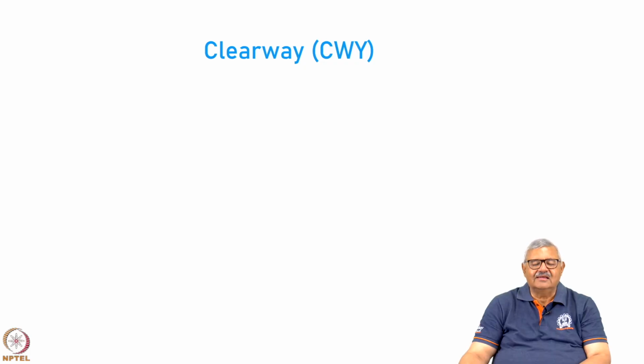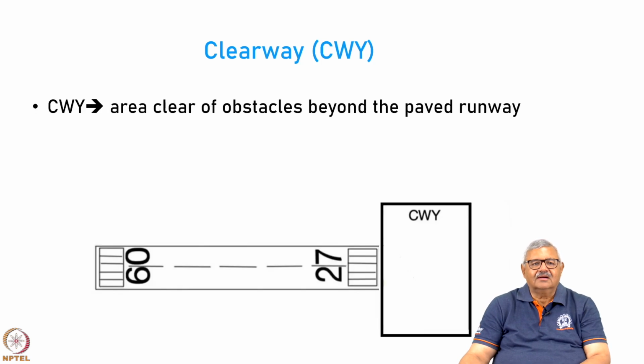Now, there are some concepts which we need to understand regarding an airport. There is a concept called a clearway, abbreviated as CWY or sometimes only CW. A clearway is an area that is clear of obstacles beyond the paved runway. This area has to be under the positive control of the airport authorities, but it need not be paved because we do not expect the aircraft to actually physically go on the clearway.